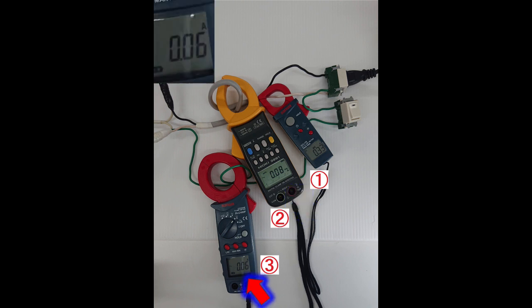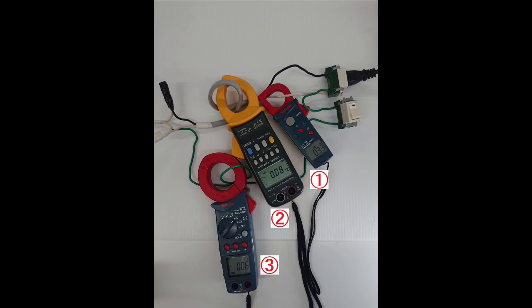For clamp 3, the electricity has increased from 0 ampere to 0.06 ampere. This is because the leakage circuit switch was turned on, so electricity is flowing to this side as well. The measured values for clamps 1 to 3 do not match the calculations due to errors in the measuring instruments. The current value measured by the earth leakage fire alarm that monitors the current value of the Class B grounding of the high voltage transformer, which will be explained later, is clamp 3. If this value exceeds the set value, an alarm will sound to notify you of an abnormality.